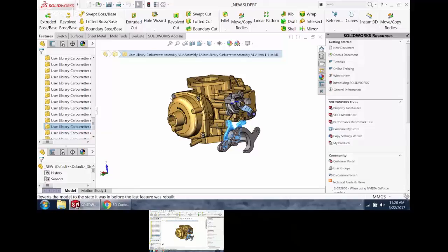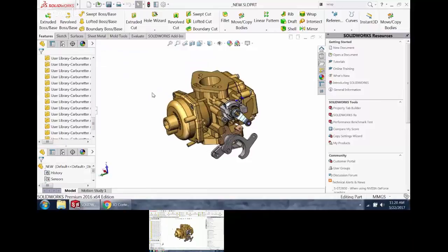Yes. Exterior faces is quite a bit faster. You just say it's faces. Oh, yeah. That's faster than setting the body for opening. Right, and it's a smaller file. It's just that you can't really do anything with it. You're stuck with how the geometry is. If you wanted to start recognizing features or cutting faces, none of that works. You do a PCB with 2,000 components, faces. Go with faces, if you don't have to know.